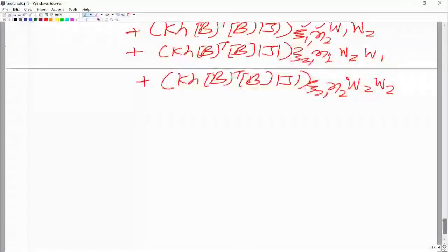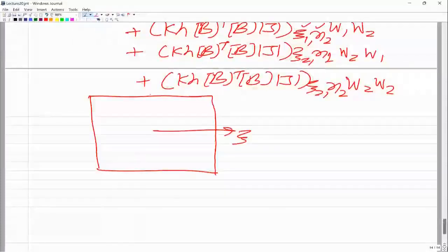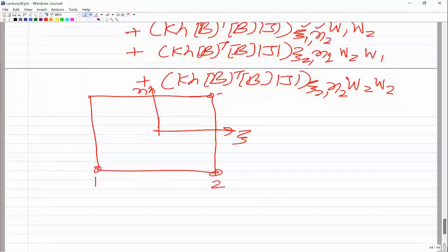Here, in finite element software also, you will see the concept of number of integration points. Now in the xi eta coordinate space, these are the nodes, local node numbers 1, 2, 3 and 4, and then you have the Gauss points. For the 2 by 2 integration, the Gauss points are inside the element. One Gauss point would be here, and the natural coordinates of this Gauss point are minus 1 upon root 3, minus 1 upon root 3.